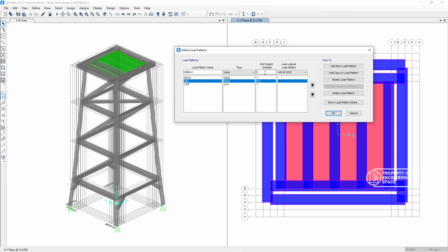Because the Indonesian standard is not contained in this section, I think we need to put in the other load pattern that was automatically generated. So I think it will be equal to ASCE in this case. I think it doesn't matter. Later we're going to try to redefine some that may not be similar to the Indonesian standard.